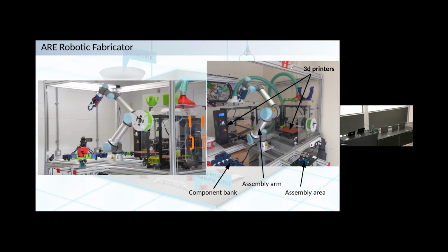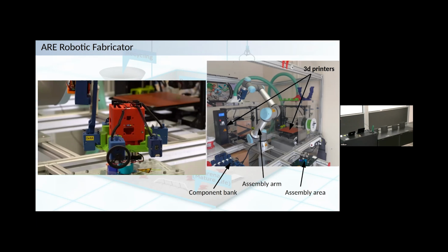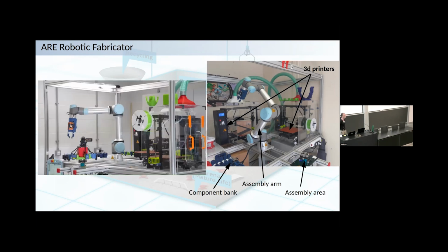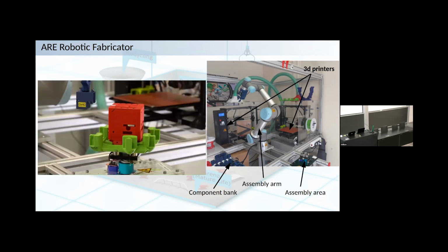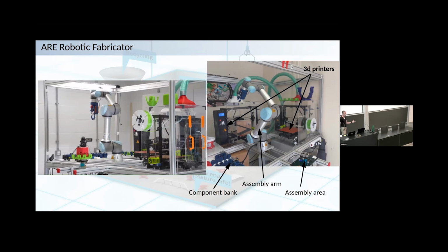So you can count on building one robot a day, between half a day and a day, depending on the robot. To speed up the printing, we have two 3D printers to be able to parallelize the printing of robots if you want to evaluate several robots. We also use low resolution printing with a large nozzle to speed up the printing, which is much faster than high resolution printing.